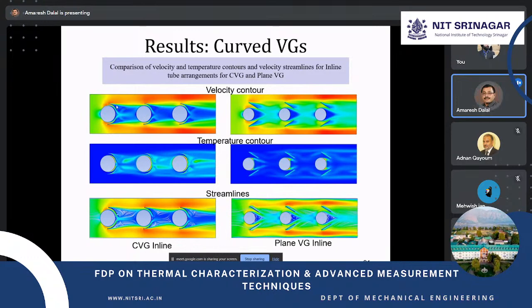You can see in this case it is gradually changing, but here when it is flowing inside, it has more velocity and it takes away more heat from here. Behind the cylinder there will also be some vortices due to the presence of this, and that way it enhances more heat transfer in the case of the curved surface. Yes, sir. Thank you so much.